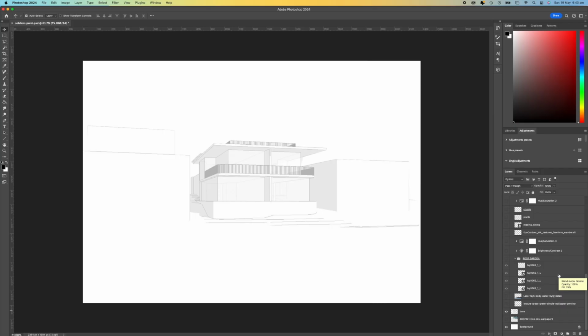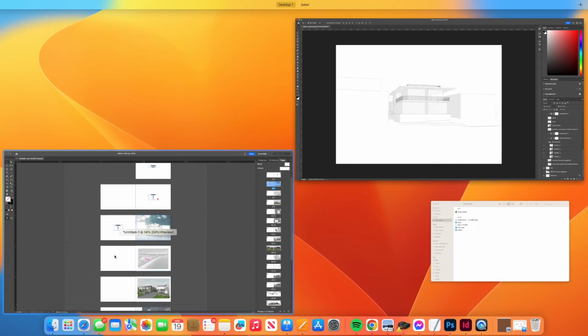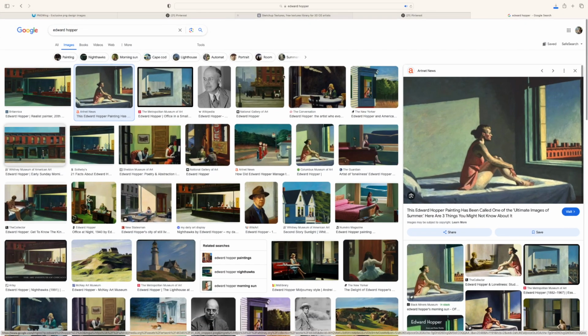Okay, so this is the base model that I started off with. I usually start with a very simple CAD model that gives us a little bit of context, and trying to save it with a very light line weight is important to get a really crisp finish. Unfortunately, I got this from a project that was done a few years ago and hadn't really learnt that, so you'll be able to see in my demonstration today how important line weight is, and just making sure that you don't get these white gaps everywhere.